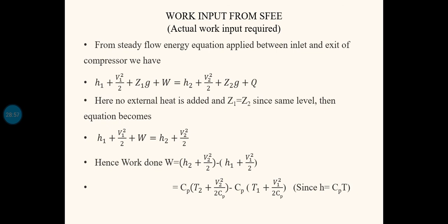So once the fluid reaches the stagnation condition, velocity will be 0. That means h increases. Correspondingly, there will be an increase in the enthalpy. That loss in velocity is actually added along with the enthalpy. So stagnation enthalpy can be defined in another way as the maximum enthalpy of the fluid, or usually it is taken as a reference condition. So that is what is known as h naught. So h naught is equal to h plus V square by 2.